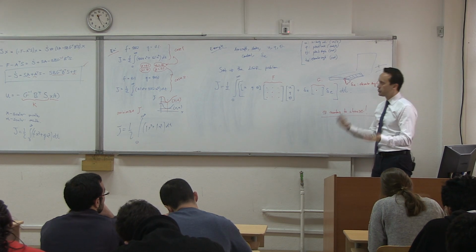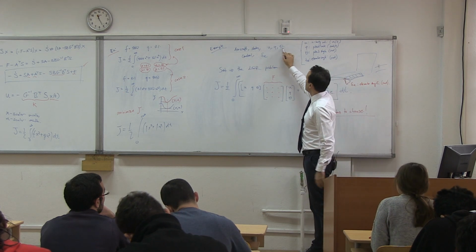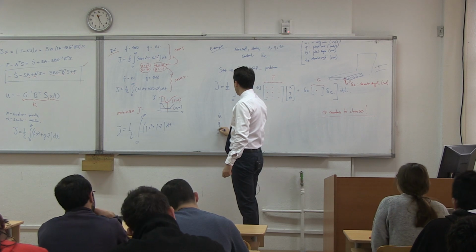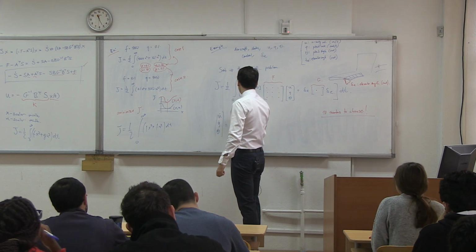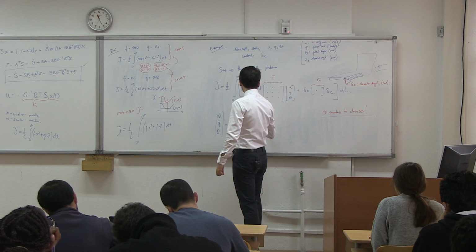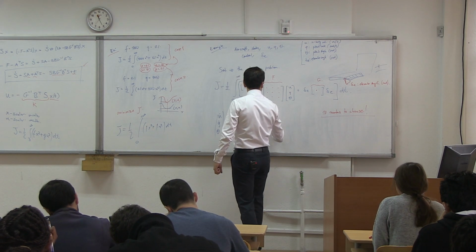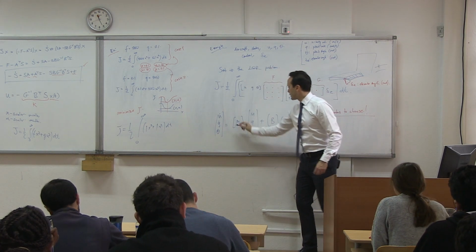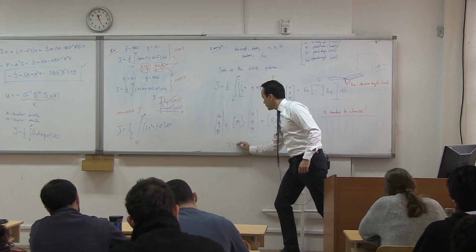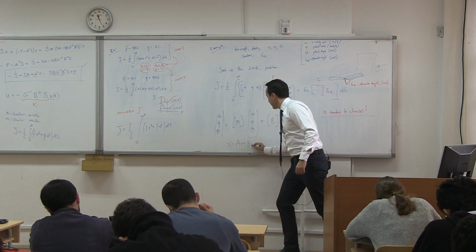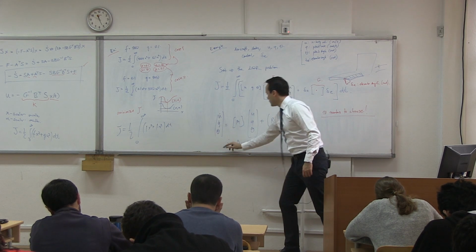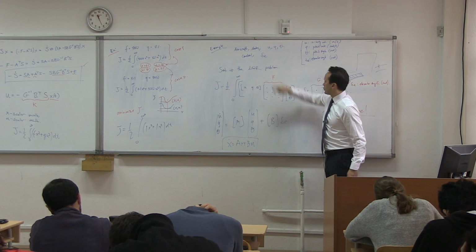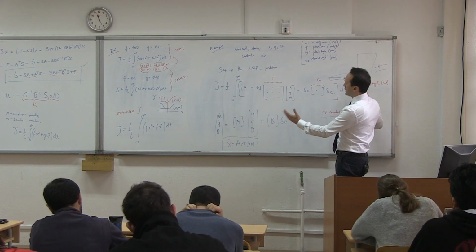So we are going to design a controller where the states are U, Q, theta. And this is of course constrained by this: U dot, Q dot, theta dot is equal to A matrix times U, Q, theta plus B del E, right? I mean, this is x dot equals Ax plus Bu. Okay, this is that. So these are the states, this is the control, and this is my LQR problem.